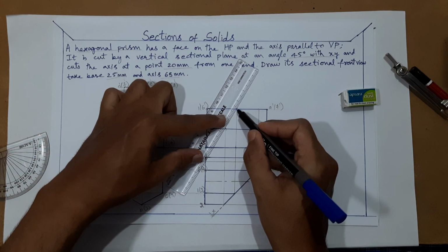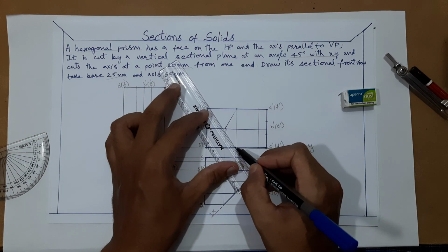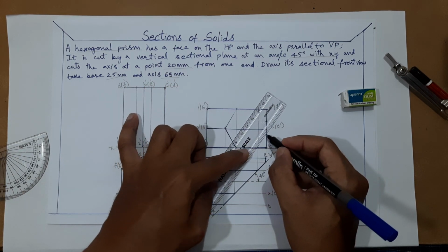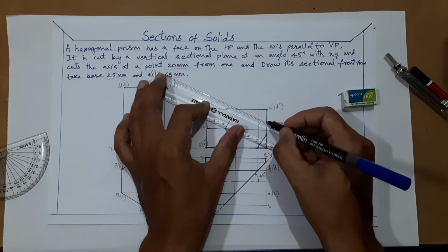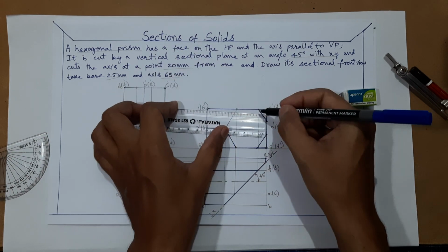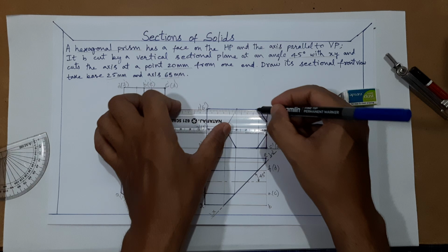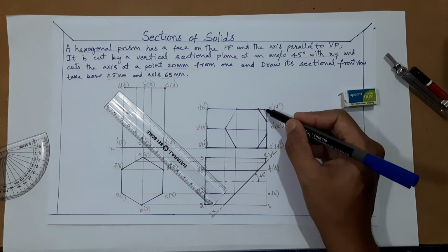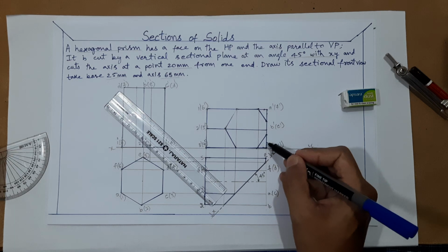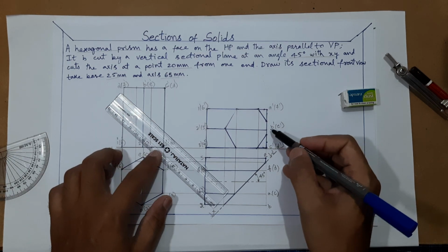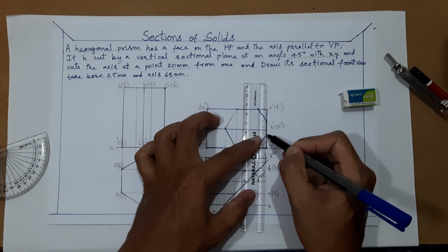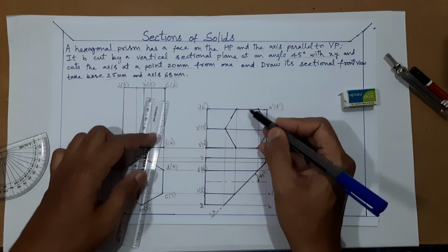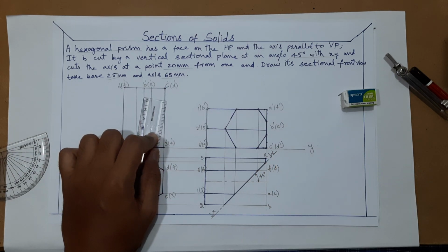Let us see. So this portion, that is this line and this line, you can make it thin, and these two lines also you can make it thin if you want, because these are not visible, and of course this line is again a darker one. So in this you have to do the hatching. Hatching are 45-degree lines equi spaced.